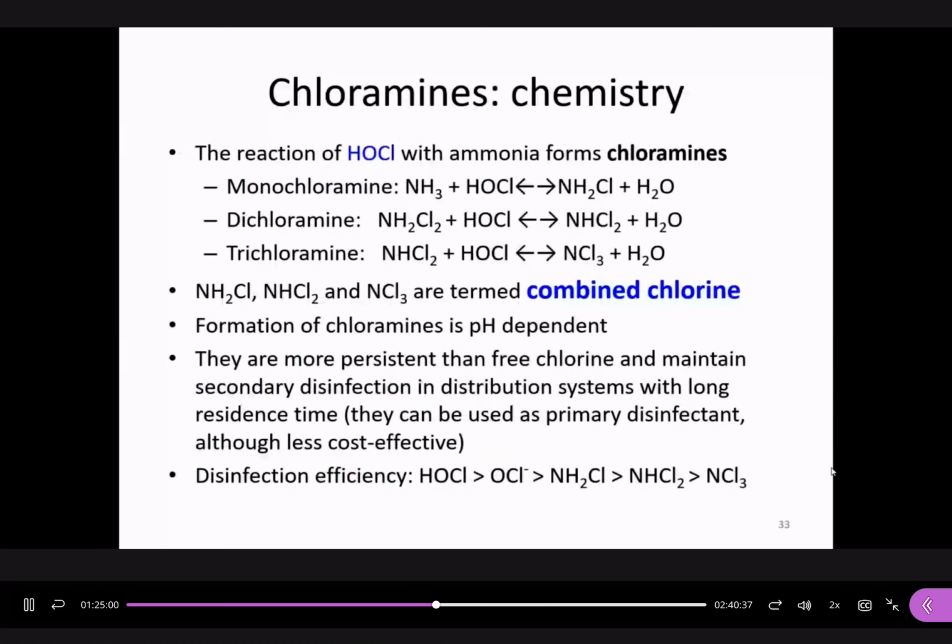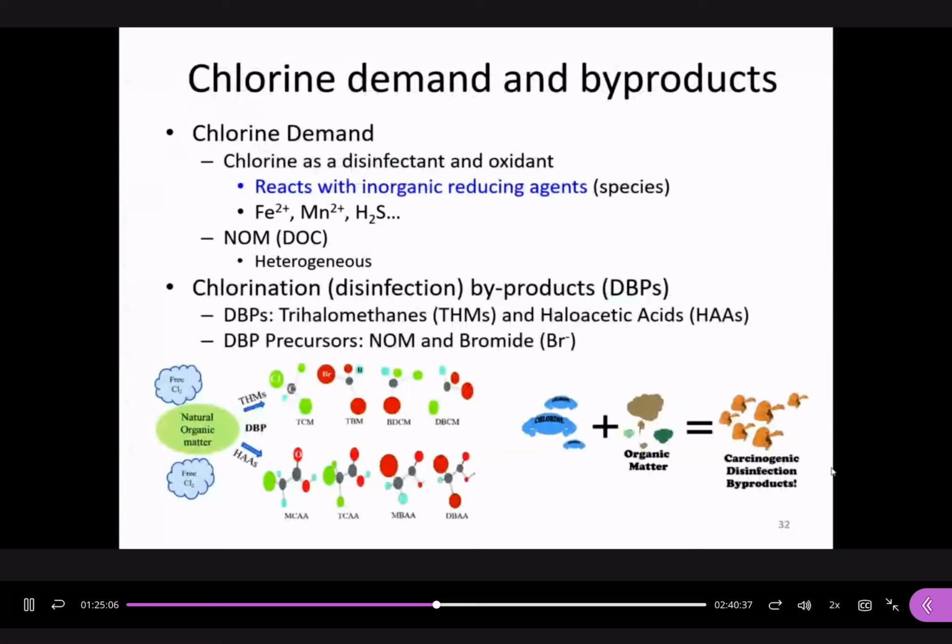Right. Chlorine disinfection. What can we do to mitigate the DBP problem? What is the most cost-effective method? Right. So we remove the so-called precursors like NOM. We remove these compounds before disinfection. Remember, ahead of disinfection, you have other steps: coagulation, flocculation, sedimentation, sand filtration. So there you try to remove natural organic matter, so that it does not stay until disinfection. By this way, you can reduce the production of DBP. Okay, so that's free chlorine.